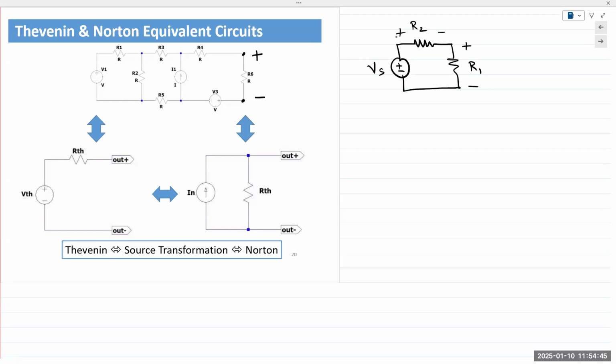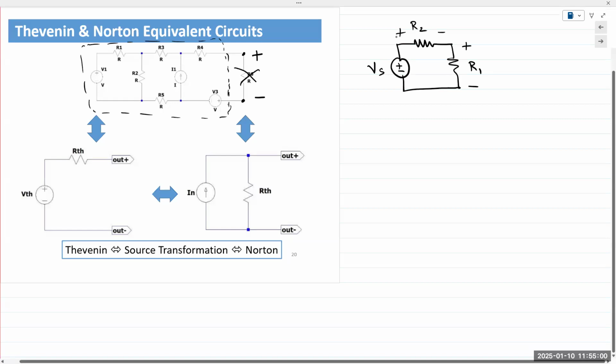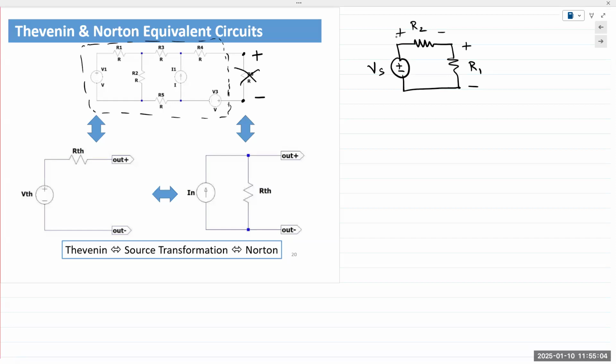Then you remove R6 from your analysis and analyze the rest of the circuit from those 2 points. And I would say those 2 points are the terminals of analysis. Okay, so you want to find the Thevenin circuit as seen by R6, and that makes a big difference.